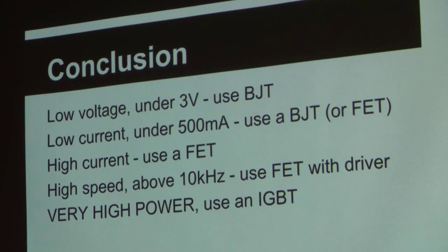Nothing that I would ever do, do I care about that? No, when you care about this is if you're trying to do a very high-speed pulse width modulation, like say you're trying to pulse width modulate something at 10 kilohertz for some reason, that's why I throw a driver out there. It's duck soup. You can make an Arduino do it. You can make a Pi do it.